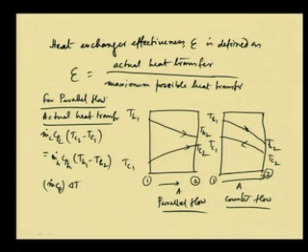We have two fluids, one hot and one cold. Now, if m dot Cp for the cold fluid is lower than m dot Cp of the hot fluid, then delta T for the cold fluid will be greater than delta T for the hot fluid.